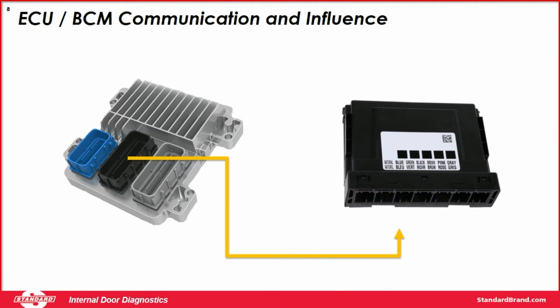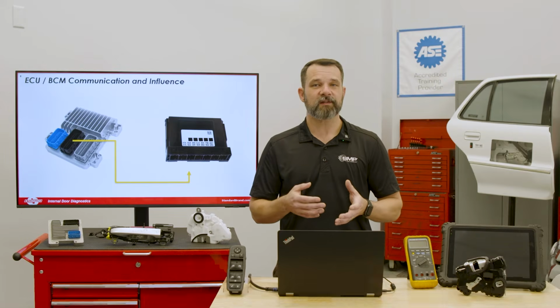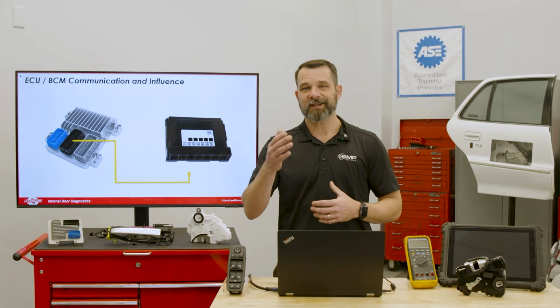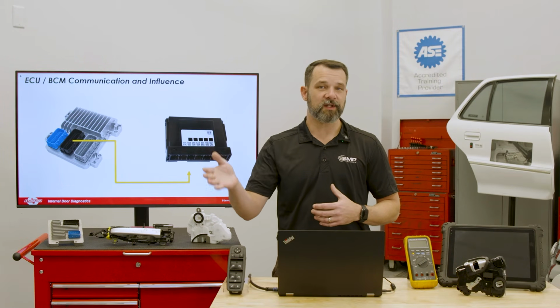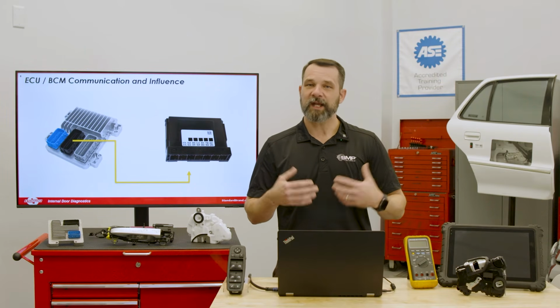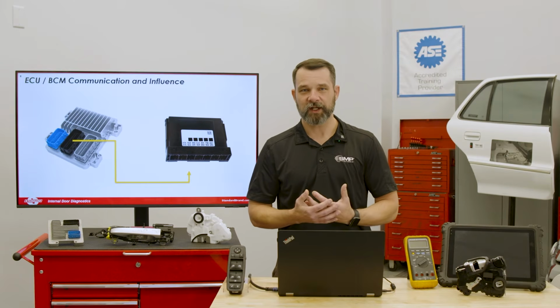And so we can see the BCM is very dependent on information from the ECU, but the ECU also depends on the BCM for critical real-time information. So things like keyless entry and push-to-start systems. The BCM verifies the key fob and sends authorization to the ECU, and then the ECU allows the engine to start. Without that BCM approval, you're not going to get a start.